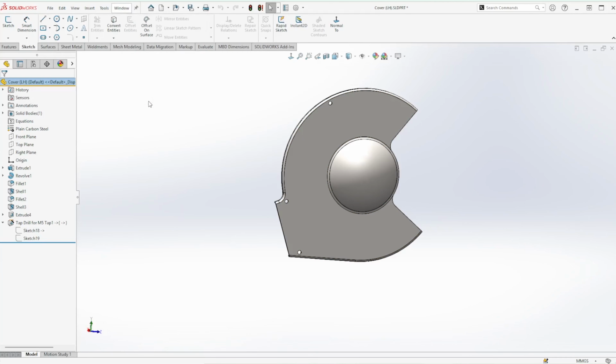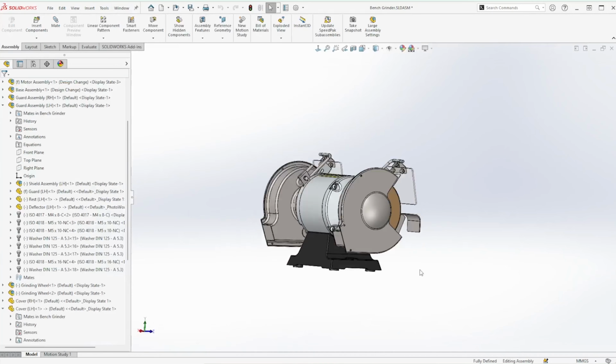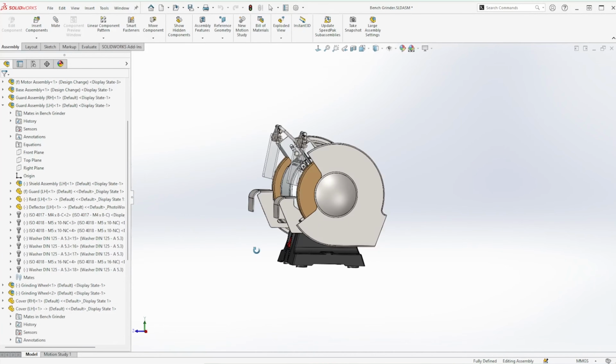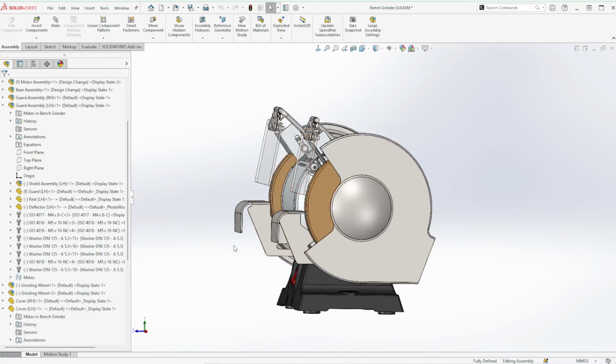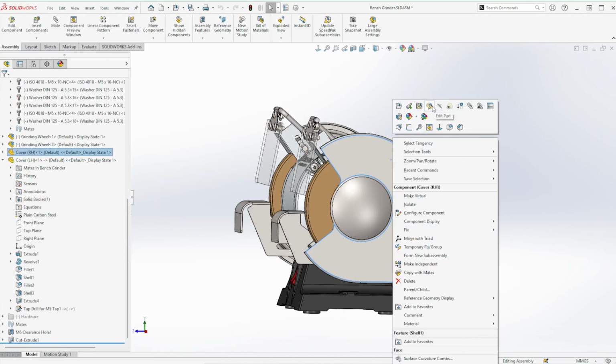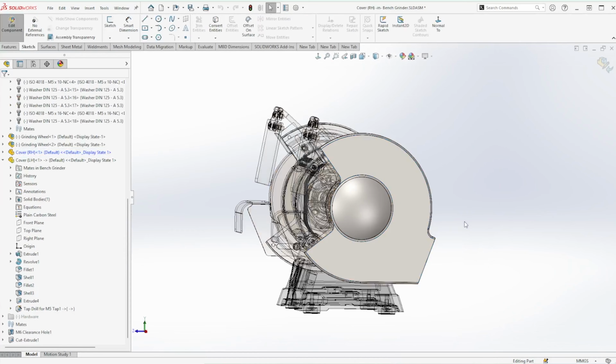Now, external references like this can become tedious to track and update when you have large, complex assemblies with lots of mates, lots of components. So sometimes we want to prevent the creation of these references as we work. I'll show you now how we could copy over those hole positions without creating a permanent external reference. So on the other side, I'll follow a similar workflow. I'll start by editing the part.